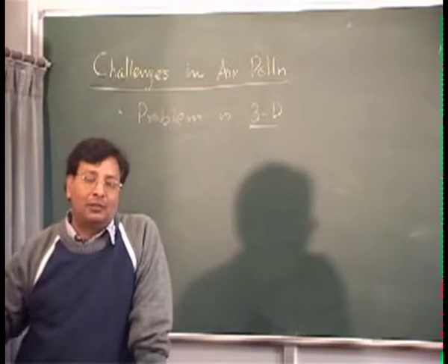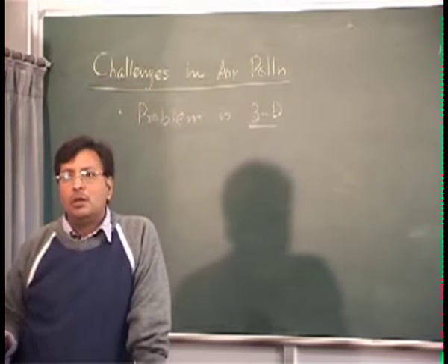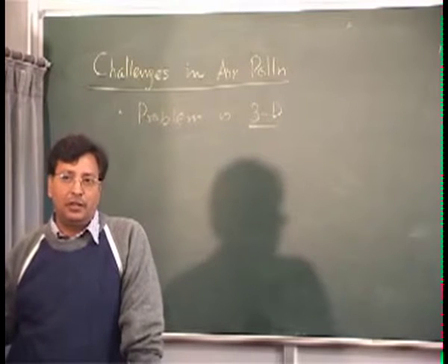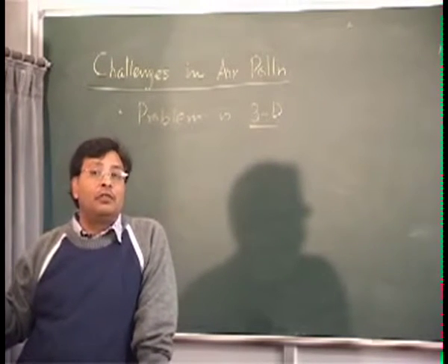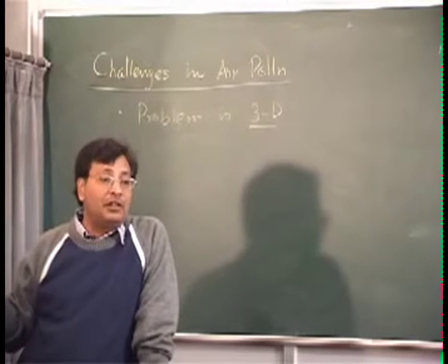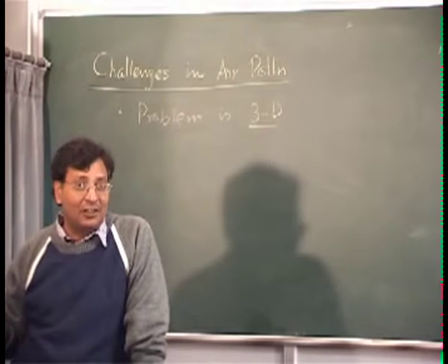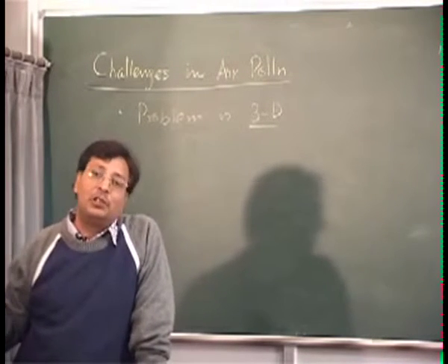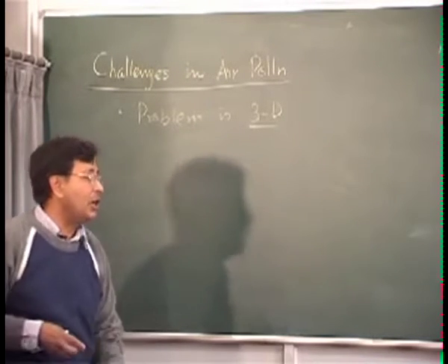Of course, some people do two dimensional also, but one dimensional modeling of the movement of groundwater as well as the transport in the vertical direction is pretty good. How do we model pollutant transport in a river? Generally 2D, whereas in air pollution, all the models you will see will be three-dimensional models. So that is a challenge when we are talking about air pollution.